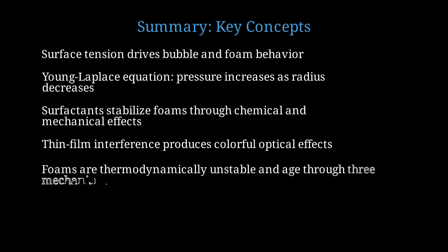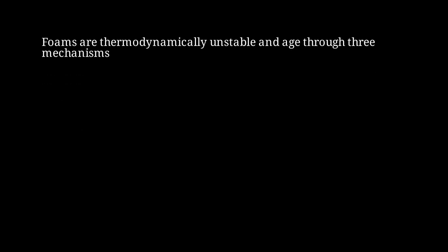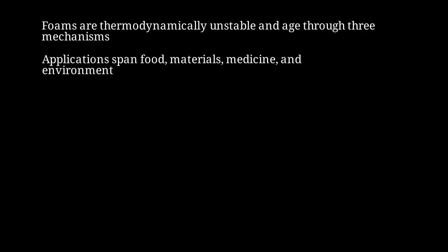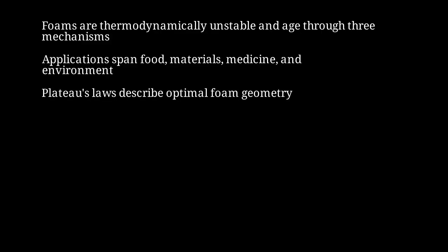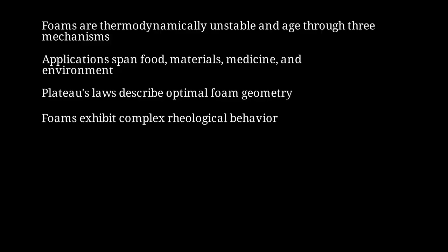Foams are thermodynamically unstable and age through drainage, coarsening, and coalescence, all driven by the tendency to minimize surface energy. Applications of bubbles and foams span an enormous range, from food science to advanced materials, from firefighting to medical imaging. Plateau's laws describe the optimal geometry of foam structures, with films meeting at 120 degrees and edges at tetrahedral angles. Foams exhibit complex non-Newtonian rheology, acting as elastic solids at low stress and viscous liquids at high stress.